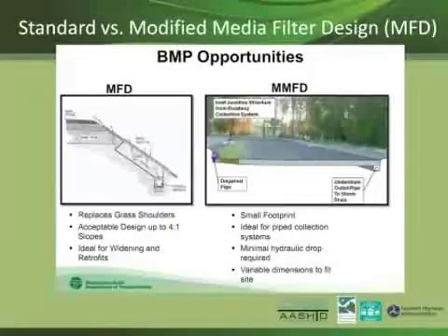We were struggling to fulfill the environmental requirement for this corridor because we have a very limited number of enhanced treatment BMPs. On the left-hand side, you can see a typical cross section for the media filter drain. In order to use this BMP, the embankment slope has to be 3-to-1 or flatter, about 33%. Most of the locations in this corridor are steeper, like 2-to-1 or so, so we cannot really use this BMP. So we came up with a different BMP. We still use the same material of the media filter drain, but we modified it a little. Instead of putting it next to the roadway embankment, we collect all the water, convey it to different locations along the roadway, and spread it out using a flow spreader. Next slide, please.